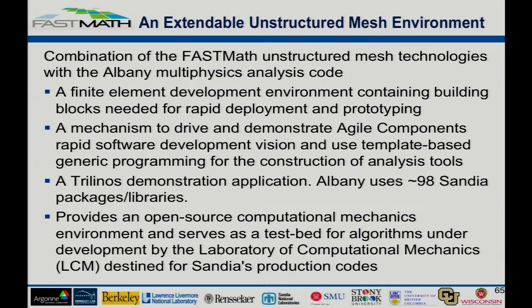And all this can be done with basically the generic template interface to the residual function that defines the physics in the code. It's a Trilinos demonstration application. We use on the order of 98 different Sandia packages and libraries, depending on what type of Albany executable you want to design. You can put one together that's just basically mechanics, or you can add a lot of additional capabilities, at which point you'll use more packages.